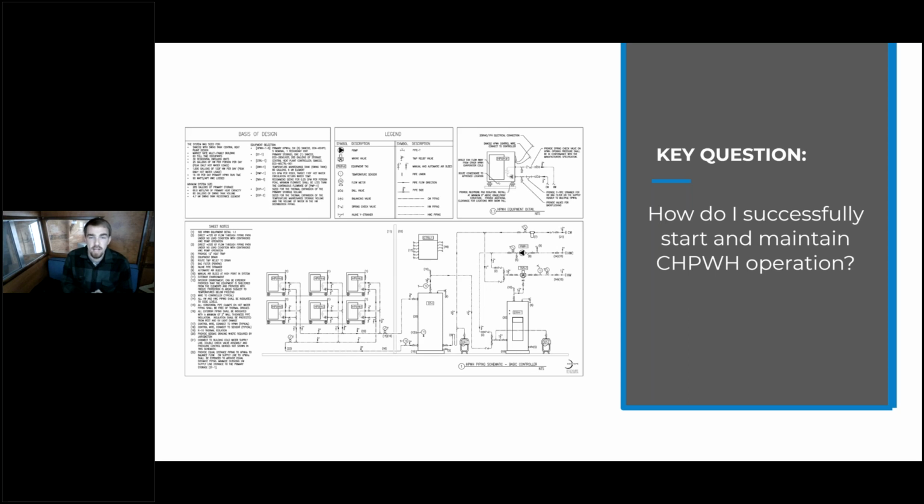Otherwise, you might have some oversights in startup that will lead to non-ideal conditions that your heat pump's operating in, and that could lead to a much less reliable operation and a much shorter life because of things like the short cycling that I was just talking about earlier. So in addition to implementing the heat pump water heater into the system correctly, you want to make sure that you follow up with a maintenance schedule, because even though it doesn't take a lot of time or money to maintain these heat pumps, you still need to make sure you hit a lot of the key points to ensure that they're still operating efficiently and that their components are cleaned and maintained as necessary.